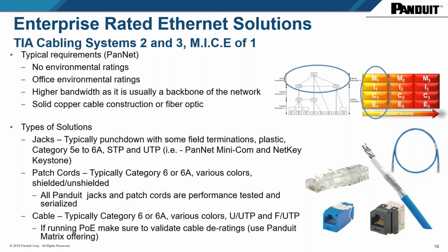And you don't have to worry about the shielding. You don't have to worry about twisted pairs. You don't have to worry about the long distances and the hardness on the cable. A lot of these plastic type RJ45 connections, which you see in the office, would work just fine in a factory environment at these ratings. So therefore, you don't over specify some areas.